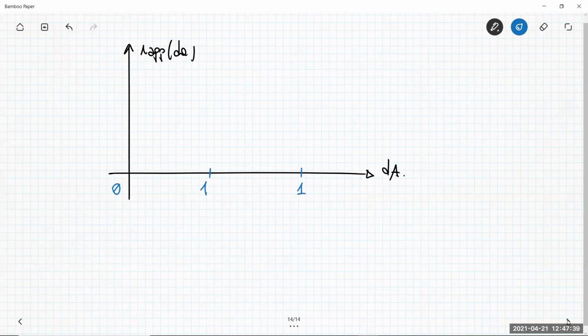When the duty cycle is 1/2, you get the maximum, and the maximum is Vd over 4 LA multiplied by Fs. In our example it is 1.25 amp.